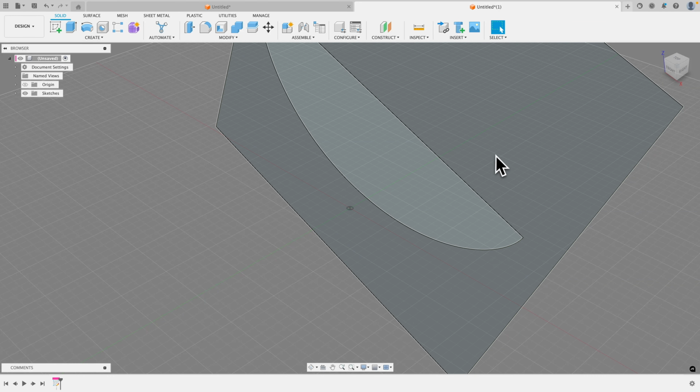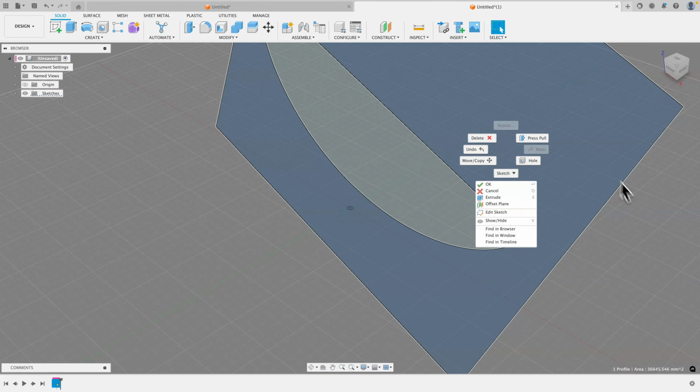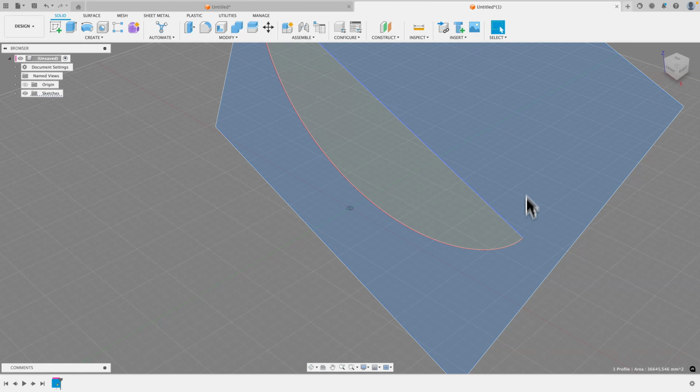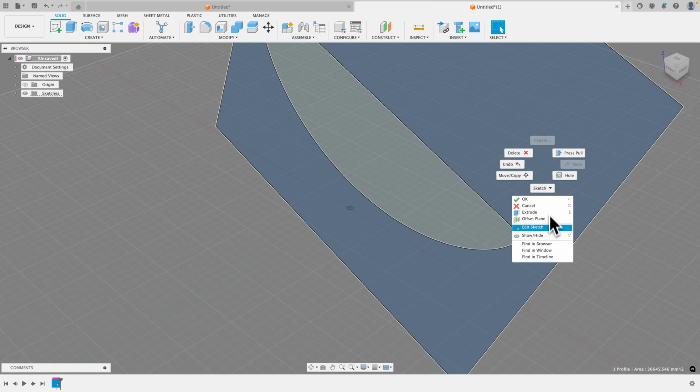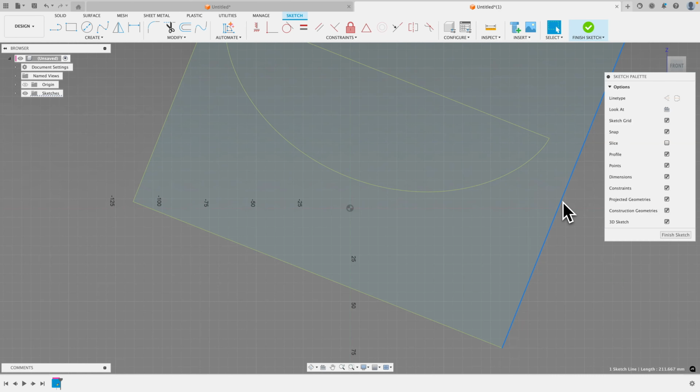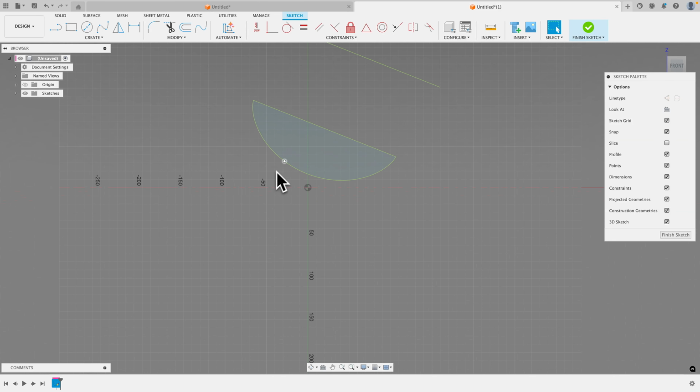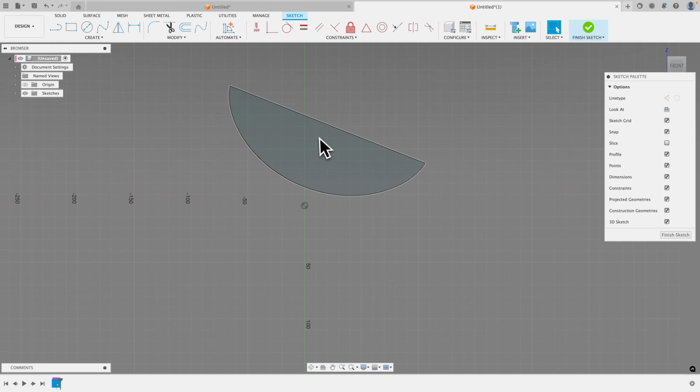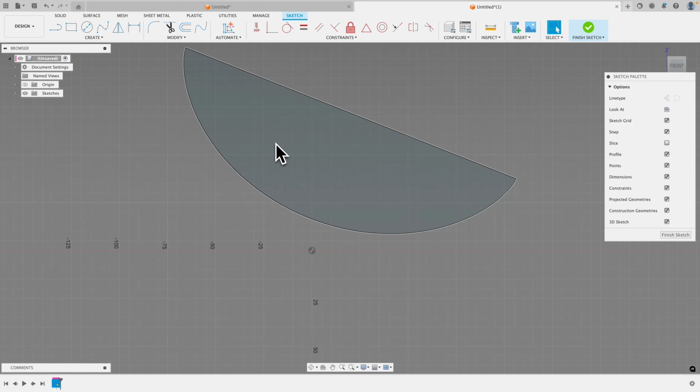The next step is editing this curve, because there is a lot of information here that we don't need. So edit the sketch, click on this line, delete it, this one too, and this one. This is not necessary but useful for later. What I want to keep is only this part. Next we will trace this cycloid curve, and that happens with the spline.